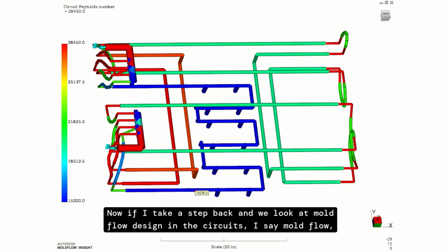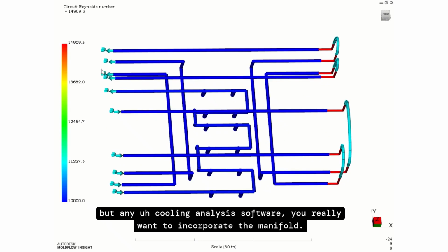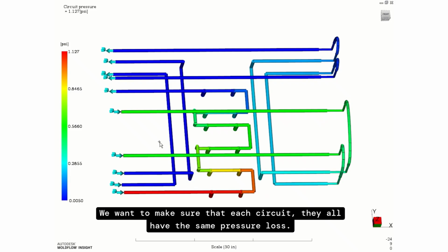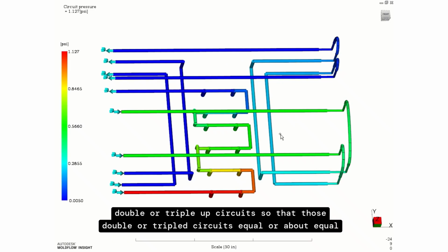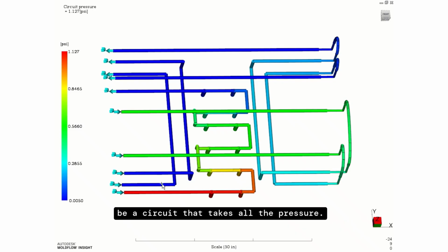Now, if I take a step back and we look at Moldflow design in the circuits, I say Moldflow, but any cooling analysis software, you really want to incorporate the manifold. But if you don't incorporate the manifold, you want to make sure that each circuit, this circuit pressure plot is one of my favorites, they all have the same pressure loss. So you have to route them differently or double or triple up circuits so that those doubled or tripled circuits are about equal to the worst, the highest demand circuit with the highest pressure drop. Once you do that and hook everything up to the manifold, there's not going to be a circuit that takes all the pressure.